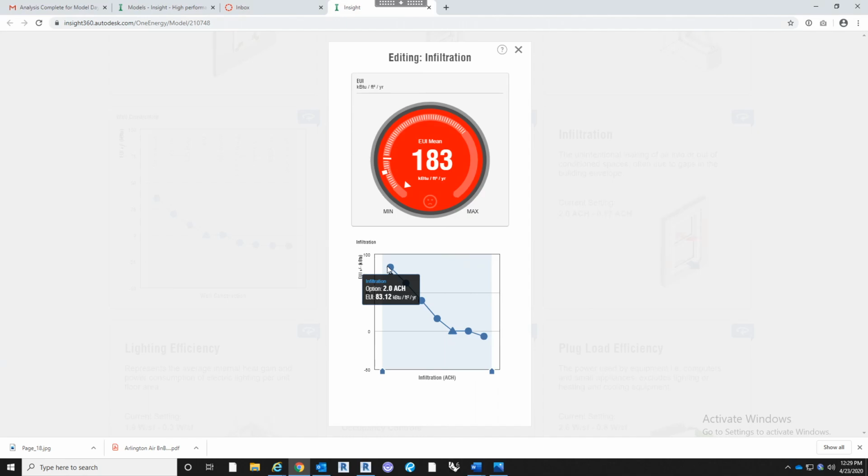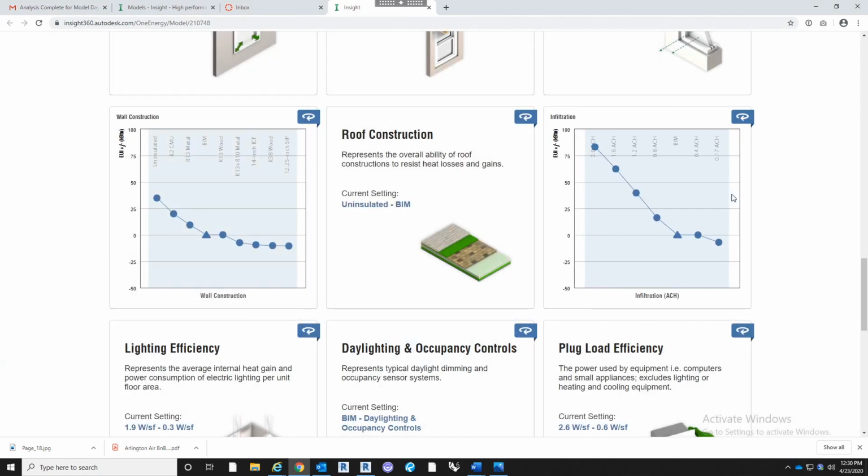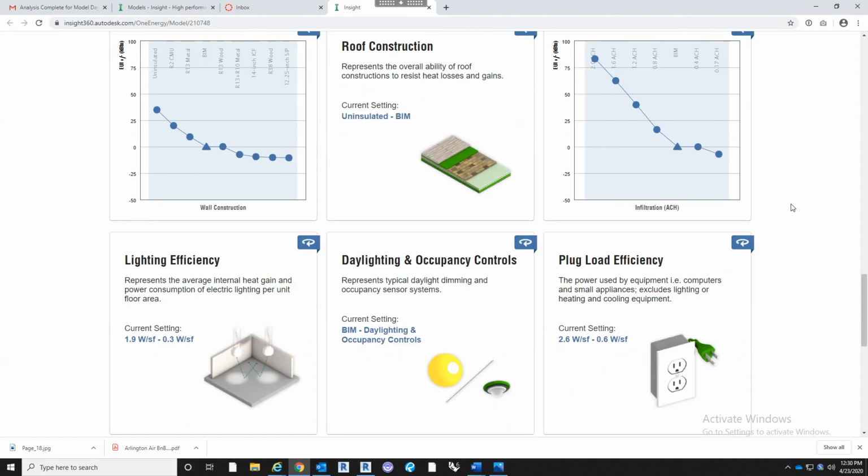So you're going to be using a lot of energy reheating or recooling that air. If you make it super airtight, you can reduce the amount because it maintains and retains that conditioned air as much as possible. We did a lot of infiltration tests where they would go around and test all the different gaps for air leakage.